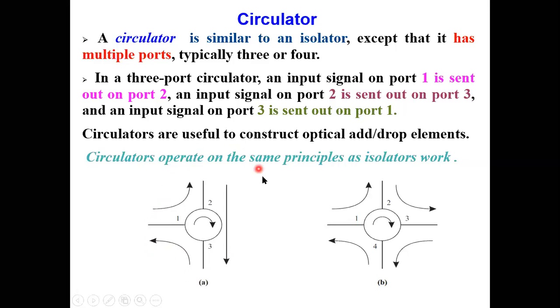I hope you understand from this diagram the difference between a circulator and a coupler. In a coupler, we have one incoming signal that is sent through the other ports. Some ports might receive a high signal, some might receive little, some might be an isolation port, where the signal does not come out.